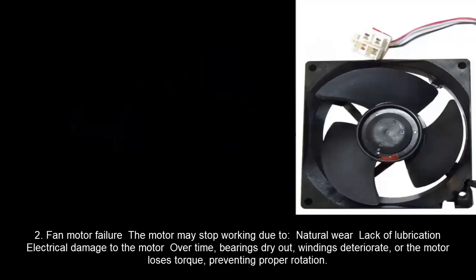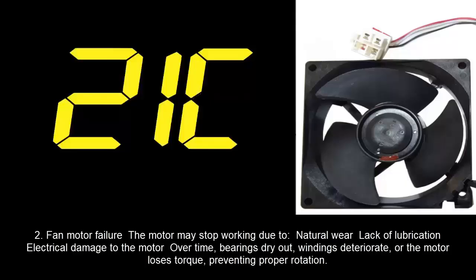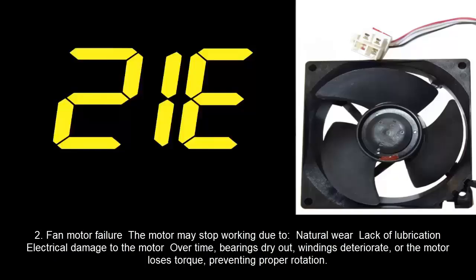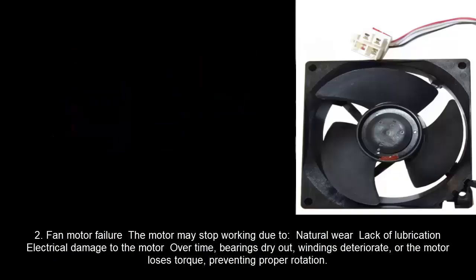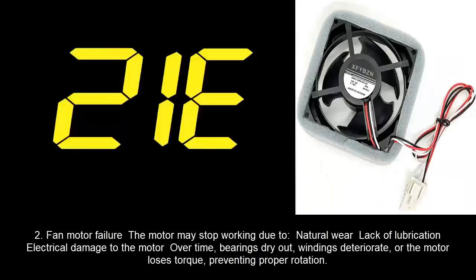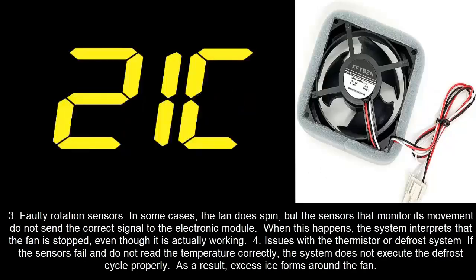2. Fan motor failure. The motor may stop working due to natural wear, lack of lubrication, or electrical damage to the motor. Over time, bearings dry out, windings deteriorate, or the motor loses torque, preventing proper rotation.